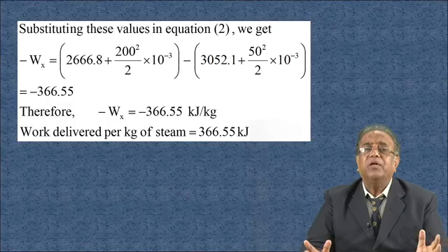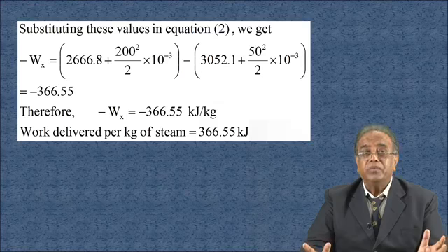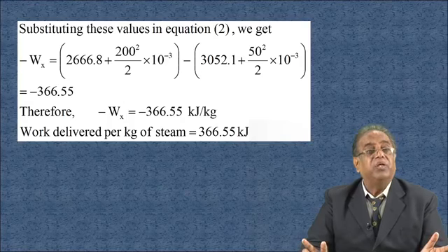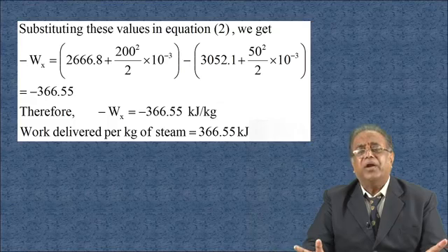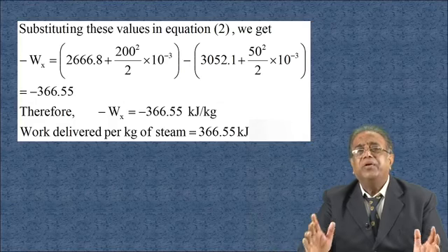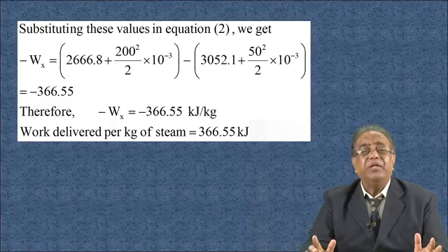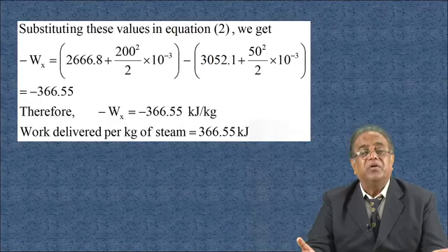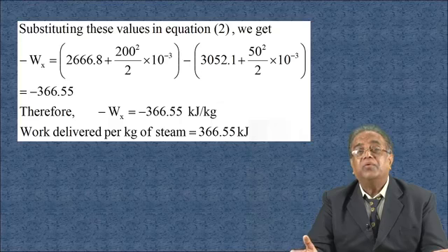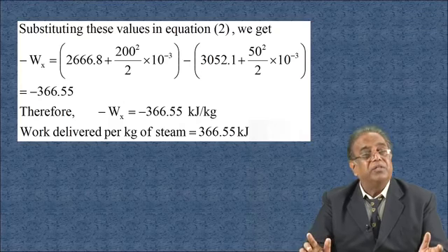After that, you see what the inputs are with regard to heat. We are giving heat input Q1, and the heat loss Q2 is in the condenser. The turbine work is WT, but the net work is WT minus WP, because WP is the work done onto the system. You have to perform work onto the system. That's why the net work done is equal to WT minus WP.